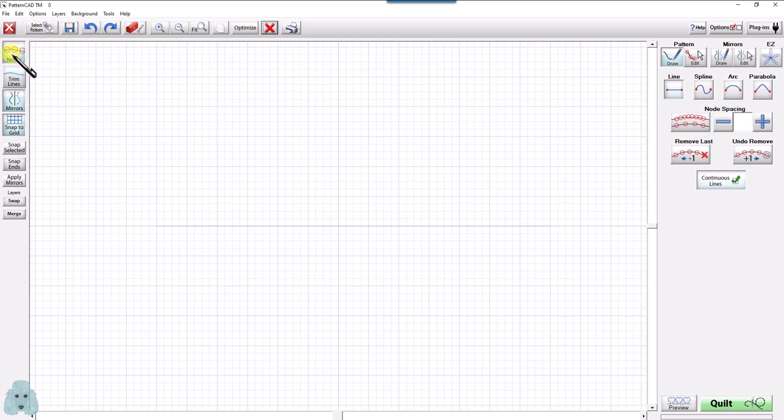Let's see, I'm in nodes, snap to grid, draw, and straight line. So I'm going to start here. I'll go up, release, go over, release, go down, release, and go over, release. Okay, I have essentially created a square. It could be a square or it could be a rectangle, depending on how you place it as a block. All I have to do is save that.